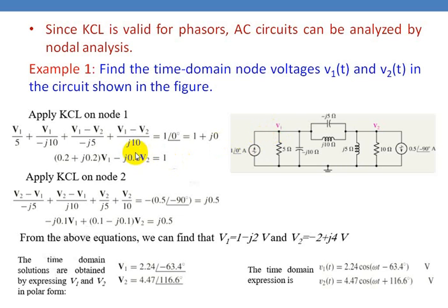So therefore, if you're going to apply Kirchhoff's current law, then we can write that sum of the incoming currents equal to sum of the outgoing currents, or algebraic sum of the currents equal to 0. So in this case, the current in this branch is outgoing, in this also it's outgoing, and the current in these two branches also outgoing, and whereas this is incoming.